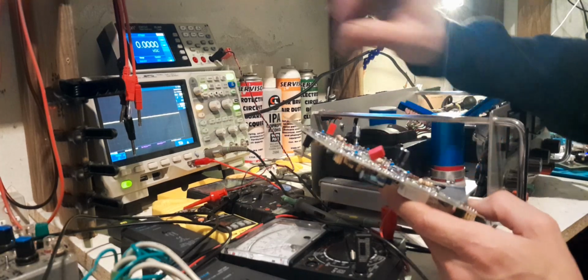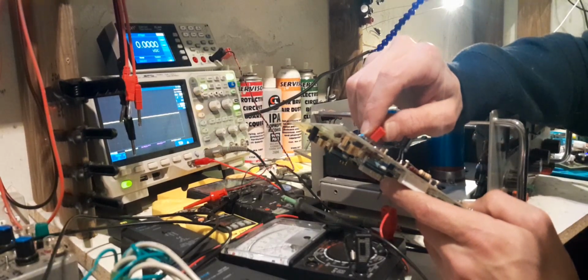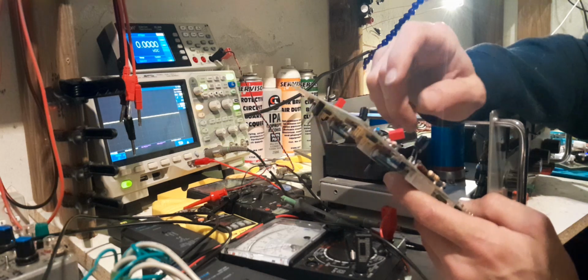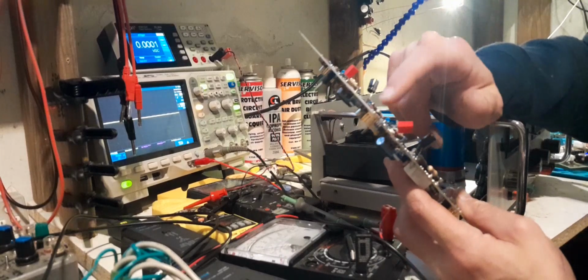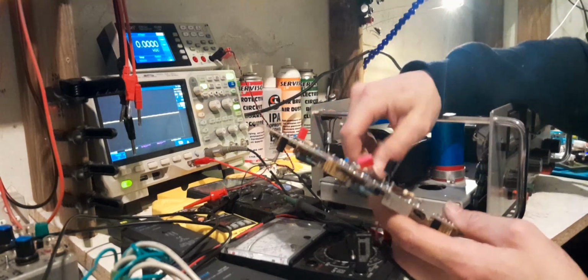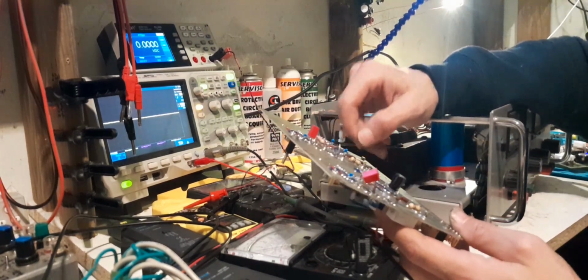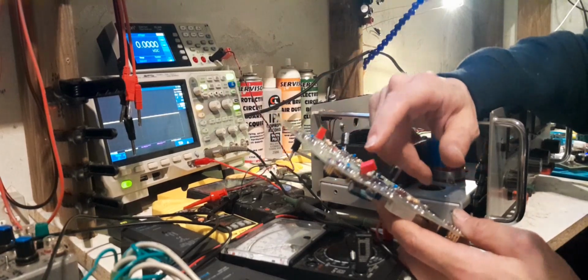Anything under that, you couldn't even see the waveform get smaller. And here's why I say I got to the point of thinking this is just not viable. To compensate this op amp to the point that the noise goes down to an appreciable level with the power supply unloaded took 1 microfarad.